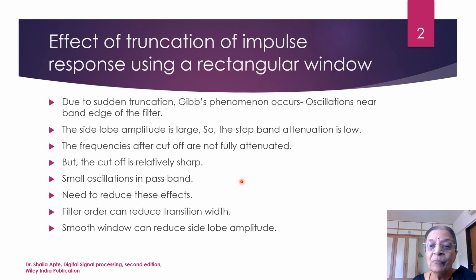And this time domain response, being a sinc function, varies between minus infinity and infinity. This is because the frequency domain response has a sudden change at the cutoff frequency. At the cutoff frequency, the response becomes suddenly equal to 0. That is why we call it the brick wall filter.